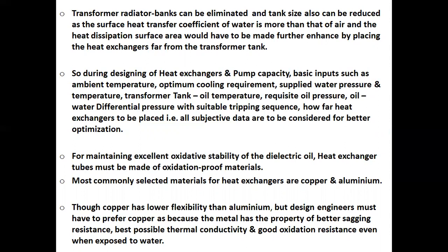So, during design of heat exchangers and pump capacity, basic inputs such as ambient temperature, optimum cooling requirement, supplied water pressure and temperature, transformer tank oil temperature, requisite oil pressure, oil-water differential pressure with suitable tripping sequence, and how far the heat exchangers are to be placed, that is, all subjective data, are to be considered for better optimization.